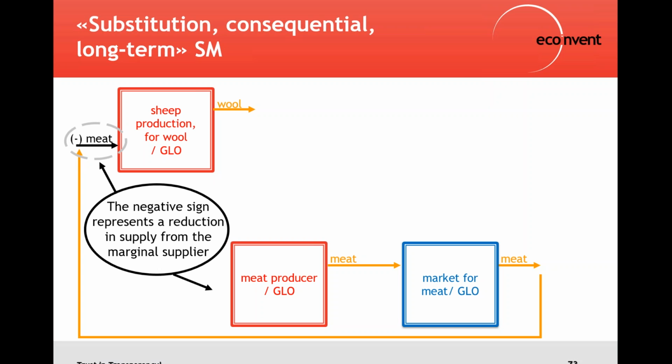Yes, exactly. That's a very good reminder. I mentioned it when I was explaining how the treatment chains get constructed. The negative sign is only allowing us to link the treatment chains as we want upstream of the waste producing activity, and we can ensure mass balance in both the waste producing activity and the waste treating activity, and that's why we use the negative sign. The negative sign is by no means affecting the results of your LCIA. So you don't get a change in the sign of your results of your impact assessment methods. This negative sign does not contribute to that. It's just modeling a mass balance activity, basically. It's just helping us to maintain mass balances. It's a mathematical trick for that.